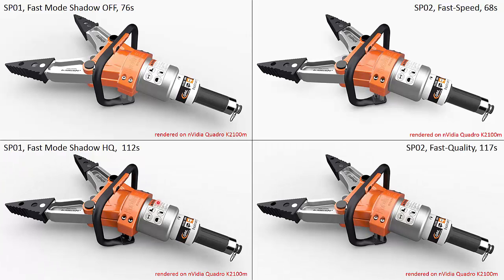so back to fast, blending in accurate on top, I think you can see quite easily how fast mode in SP1 had, well, the easiest way to describe it is it seemed as though the shadows were overdone. And in fact, they kind of were, because essentially you weren't getting all the reflections you should have gotten. You were just getting shadows. Or in some cases, if you had a reflection on a blurry surface, that reflection was there, but it was a dark reflection. It wasn't an accurate reflection.